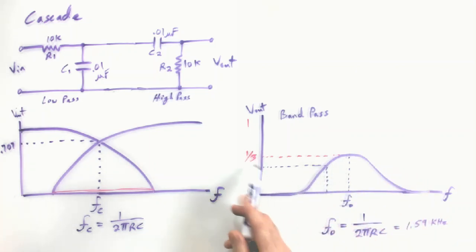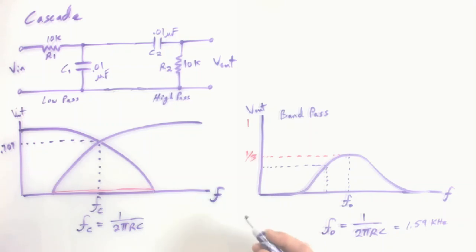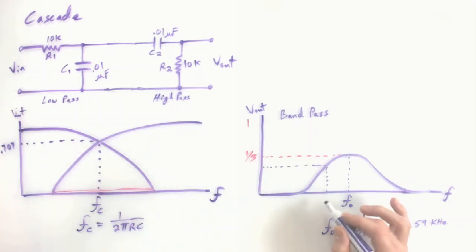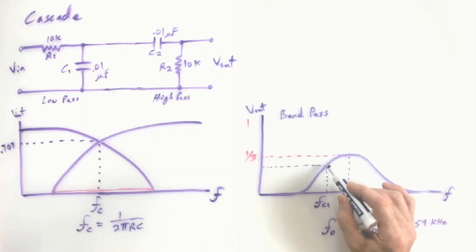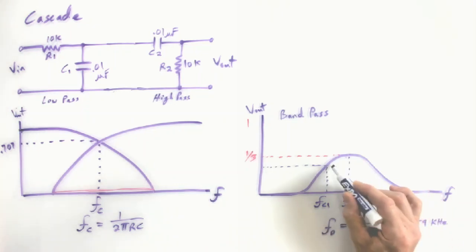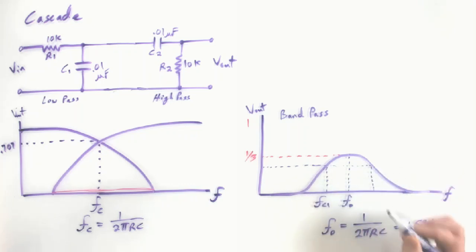So we're not talking 0.707 of the input. We're talking, in this case, I mean, again, it could be that if you had buffering and things like that. But for our simple example, this is what we want to identify as our cutoff frequency number one would be there. And again, where it drops to 0.707 as you increase the frequency would be the other cutoff frequency.